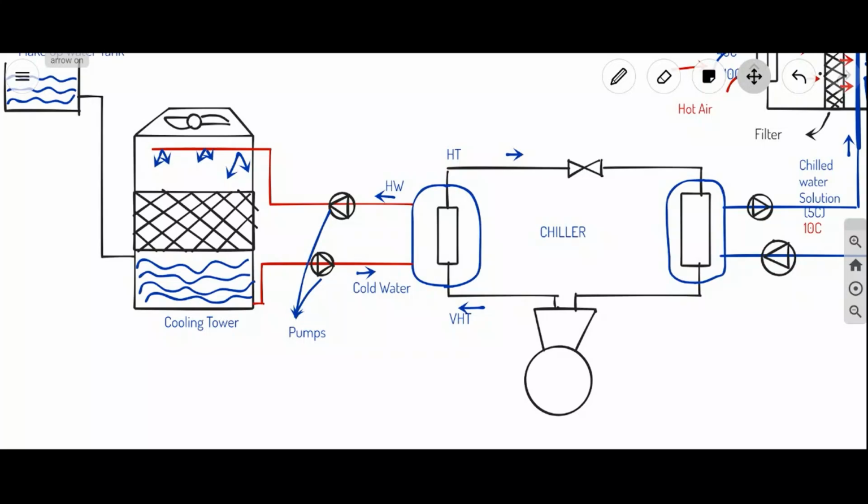In this case, the temperatures are around ambient temperatures, so no insulation is required for the piping, and this piping is called condenser piping. Now the hot refrigerant will move into the expansion valve. In the expansion valve, the refrigerant expands and becomes very low temperature, a chilled refrigerant.